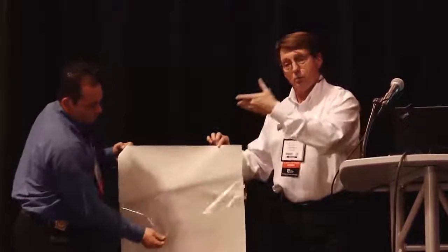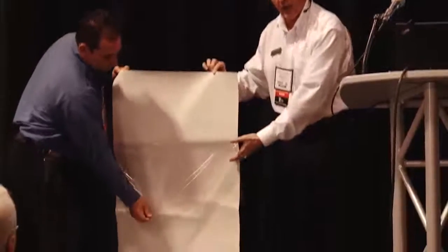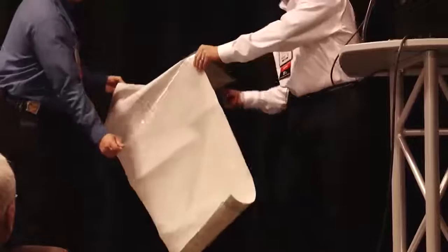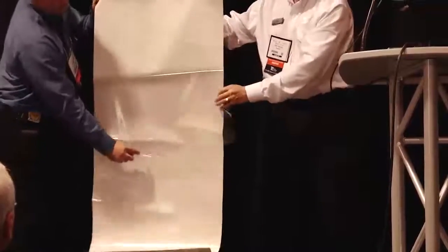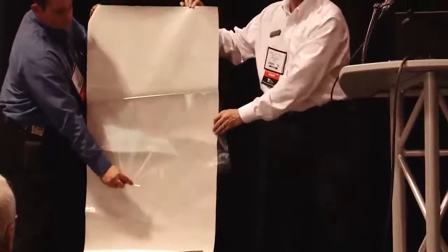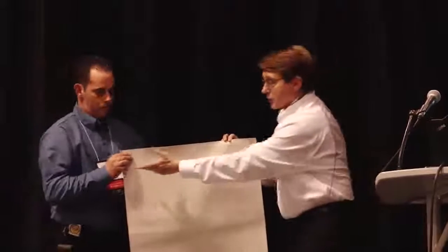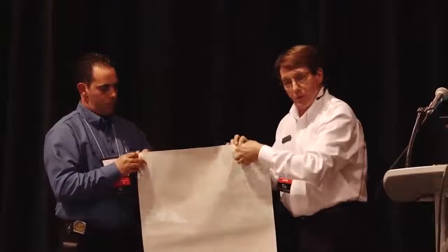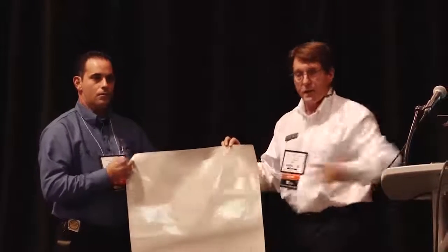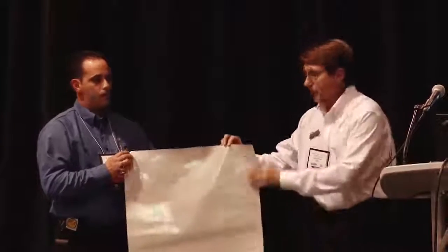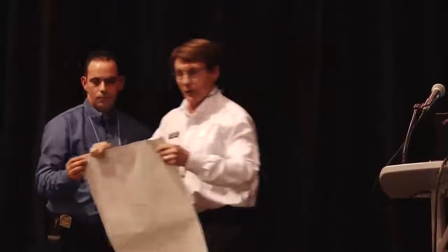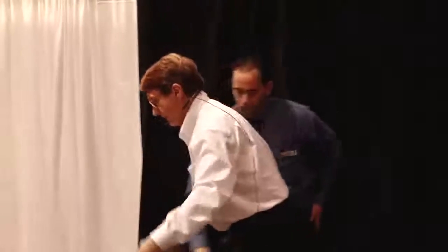But you pull the release film down as opposed to trying to pull the membrane off the release film. So if your contractors are having a rough time, they're just pulling the release film off at a different rate. In a typical installation, one may score the membrane, remove the first top 4 inches, stick it to the wall, and then pull it down, which is where we're going to start off this part of the demonstration.